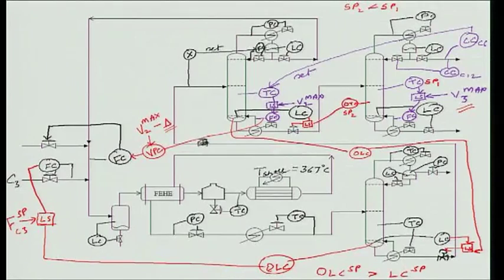At low throughputs, V3 is not active. So, because V3 is not active, temperature control is using boil up. Why is temperature control using boil up? Because the override temperature controller set point is less than the set point of the nominal controller, and what that basically does is that the override temperature controller sees that, look, my temperature of the tray is actually higher.